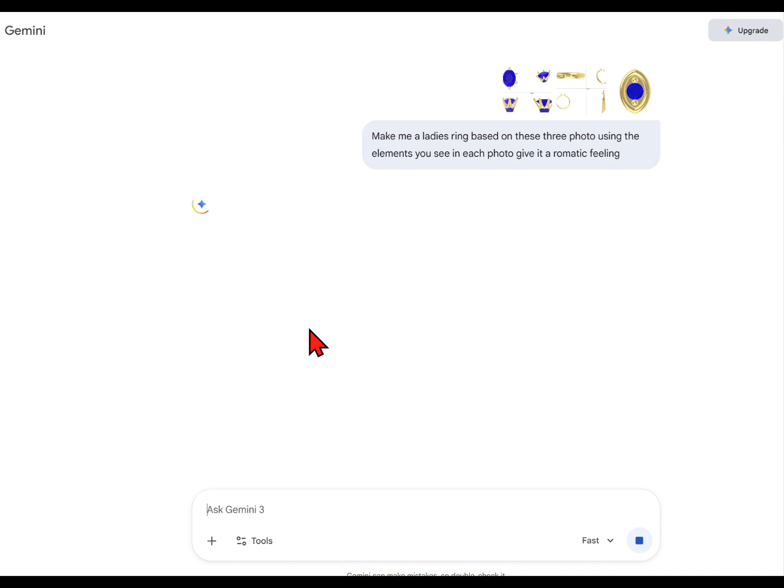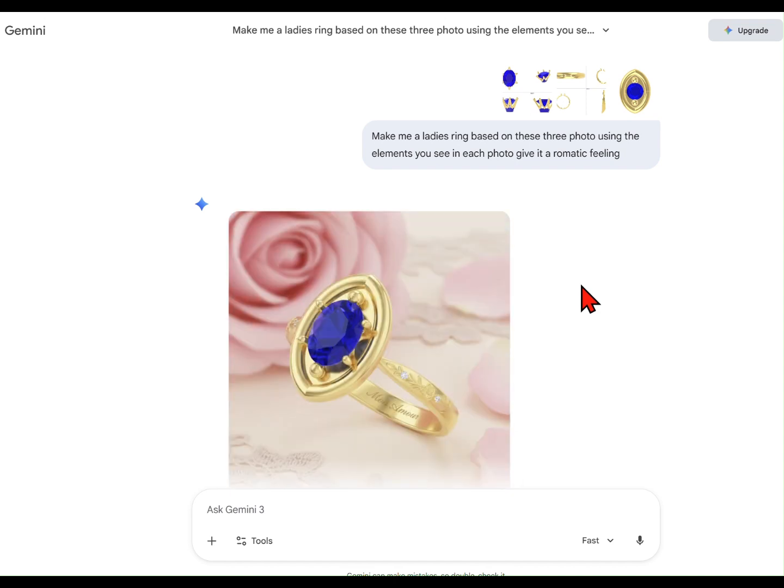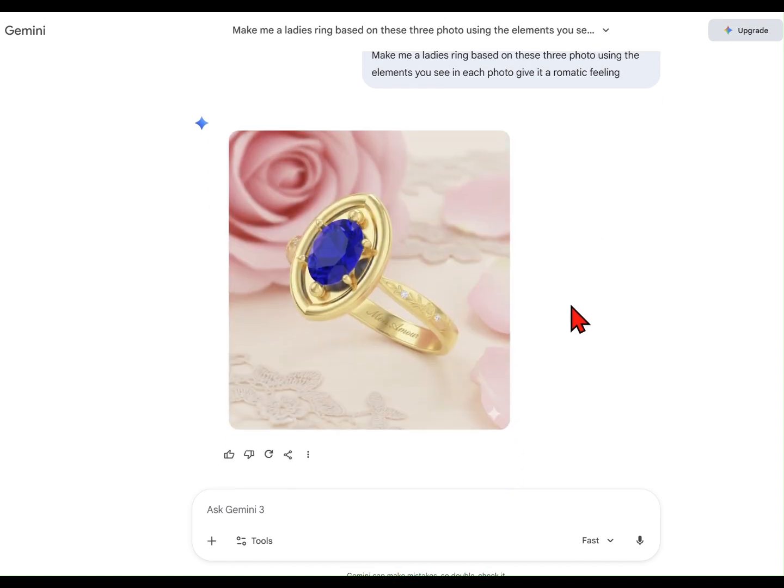That's very cool. And that creative energy carries right over into the AlgoJoule's Gemstone tab. Obviously, the engine needs perfect stone meshes to work with. That's where Gemesh Cutters 1.1 comes in. And that tool provides a full selection of meshes, round, cushion, heart, and heart halo. And they take length, width, and depth in millimeters. What's the key utility there for setting prep? It's a little slider called offset girdle from stone. Okay. See, when you create a bezel, you can't have the metal right up against the stone. You need a precise gap for fitment, for finishing. This slider instantly creates that necessary offset curve at the girdle. It's a small detail, but it saves so much time.